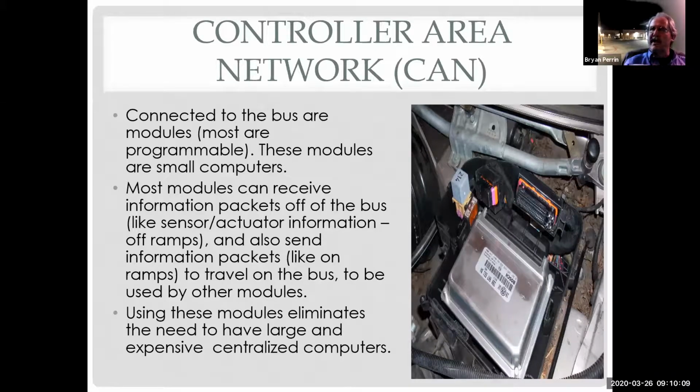Because the first thing we need to do to have a network work properly is to have everyone on the network know who else is on the network. So if I just put a module in, it may not know that we have power windows. It may not know we have power seats or heated seats or dual zone climate control or any of these other functions.